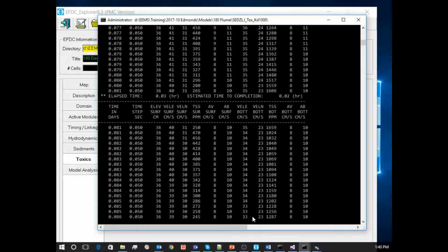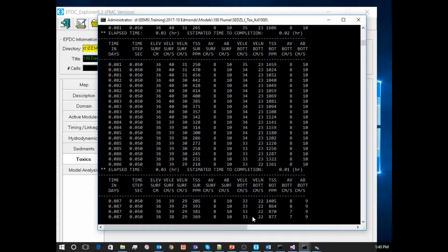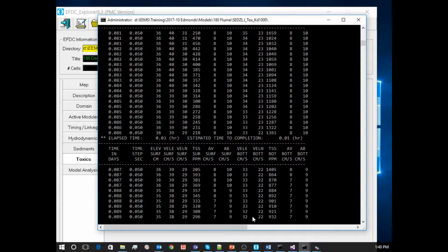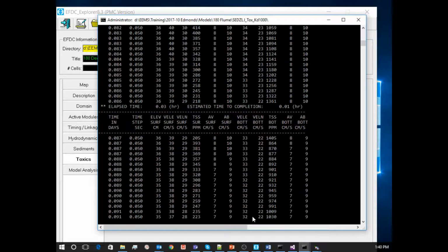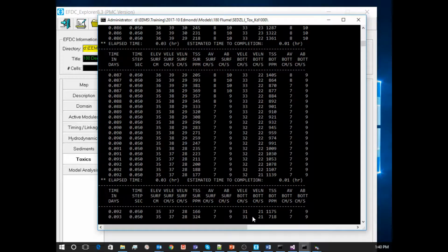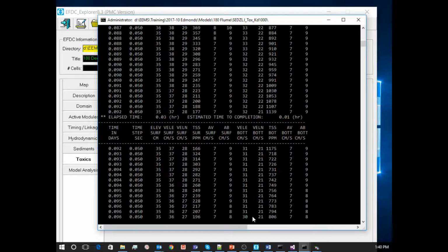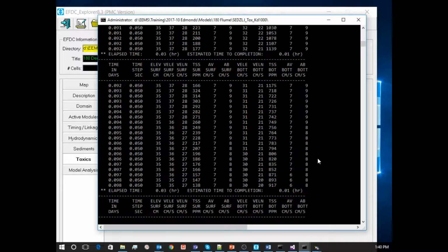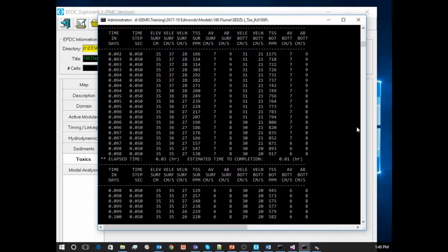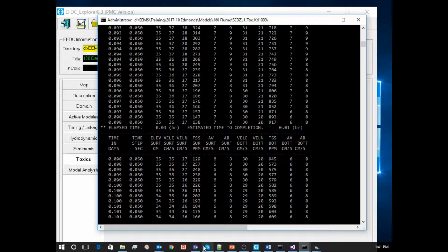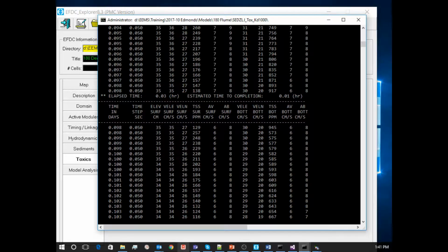That's the reason why we just don't straight up use it by default, because when you're accessing, it's bigger. The arrays are all double in size in memory, so it just slows down just a little bit. All its lookups and everything, it's about 10% slower than an equivalent single precision model.